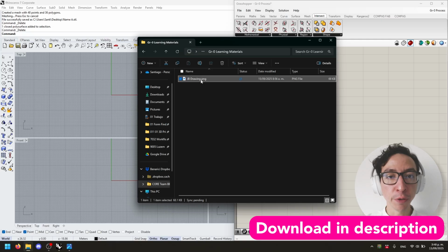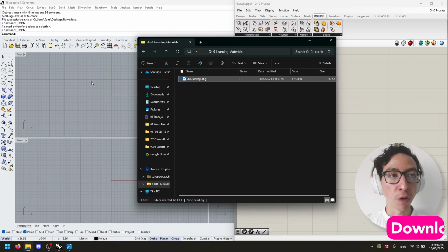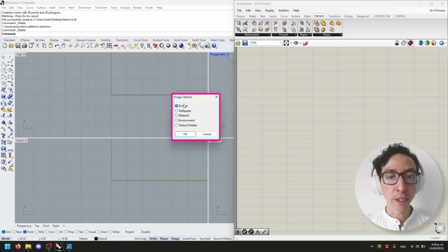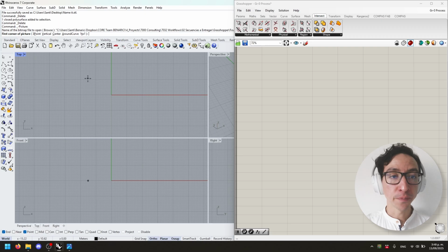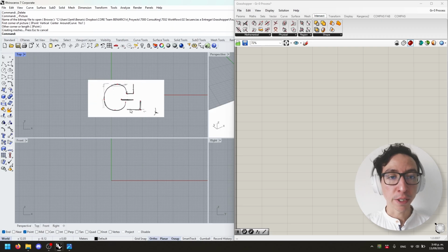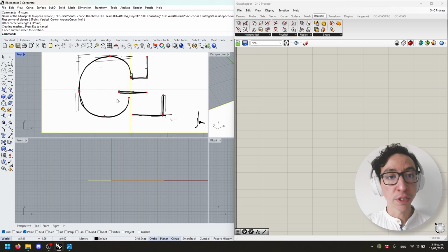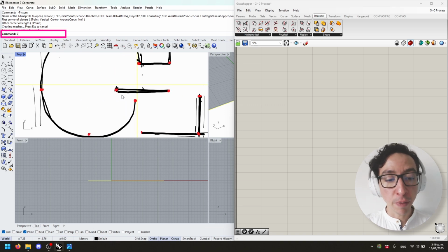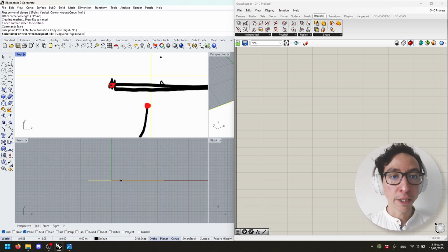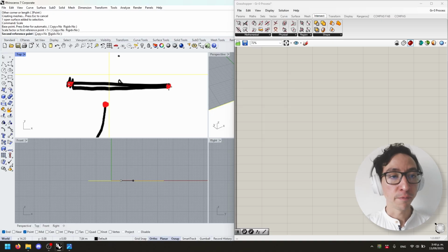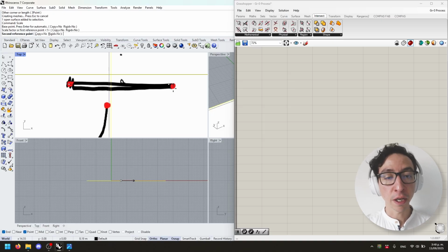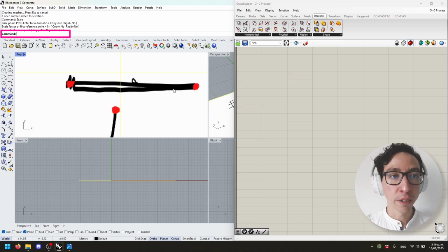So here we just drag the element and drop it over Rhino. It's asking us, and we can select that it's going to be a picture and we just place it. I'm going to scale it so that these 2 points, these red points that are the elements shaping my space, are 10 meters apart. So select the first point, then the second one, and then I write 10.